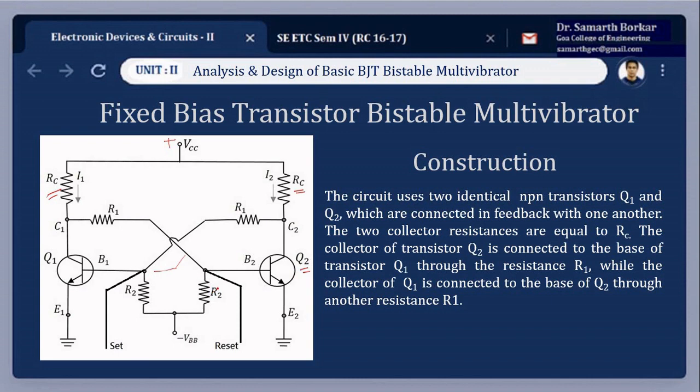The characteristics of both the transistors are never identical on account of the value of HFE, and we cannot have identical values of HFE because the technology has not been developed to keep the base region equal in all the transistors, because it is in terms of micrometers. Since the characteristics of these two transistors are never identical, after switching on the power supply, one of the transistors starts conducting ahead of the other.